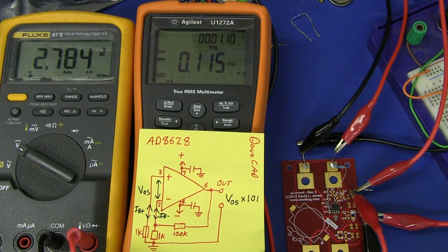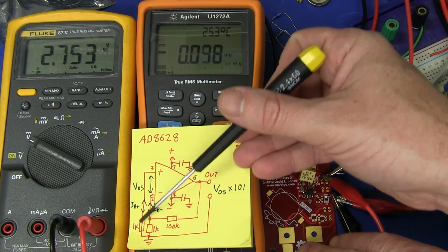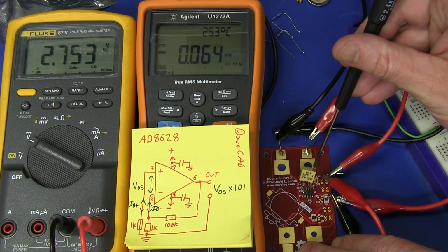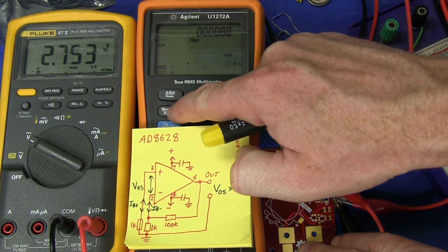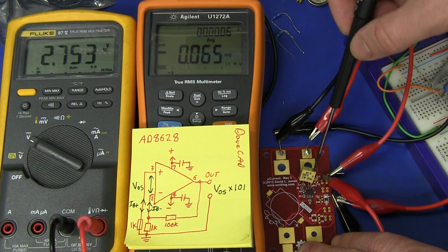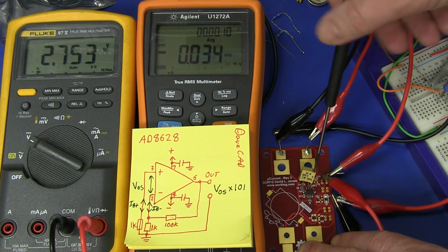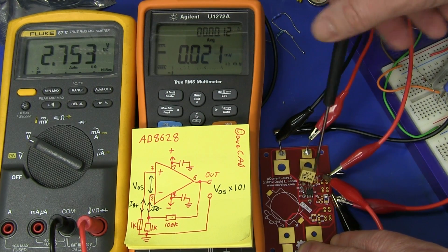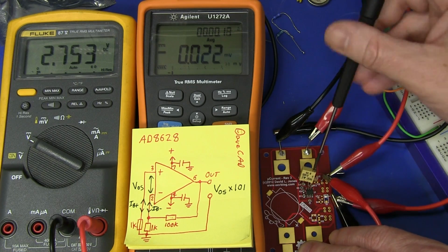then hey, that's just fine. And then if we install a 500 ohm trim pot as the bias resistor here, you'll notice that we can actually tweak it. Let's get our average there. Watch, see, it's stable. Now I can tweak this thing. Look at that, not a problem at all. So you can actually tweak your input bias currents.